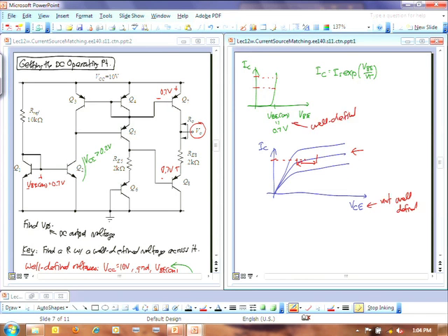Okay, so I go back to this. Yes? We're doing all of this in BJTs, but for MOS, the graphs look the same, yet we don't have a well-defined VGS. Yeah, that's because you can design your MOS. MOS is more designable, right? Depends on your W over L, depends on a lot of things. Plus, it's not as strong a nonlinearity as the exponent, right? An exponential is much stronger than the square law of an MOS. So with MOS, it's not going to be as easy as just saying 0.7 volts. You're going to have to calculate what that is based on the current going through it. But those are closed-form calculations, right? You can make those calculations.